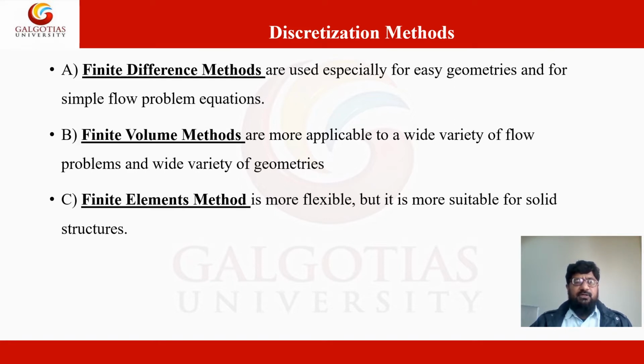So though the finite element method can be applied to any complex geometry, it has slightly less accuracy in comparison to the finite volume method. And the finite difference method has the highest accuracy, but it can only be applied to simple flow problems which have easy geometry.